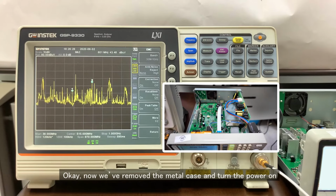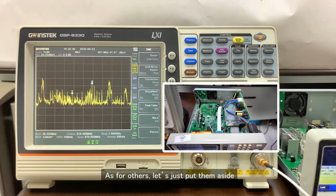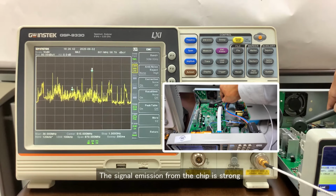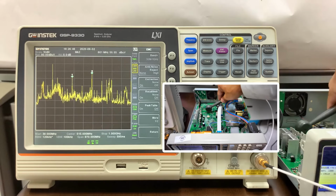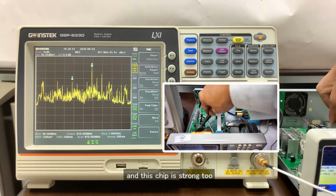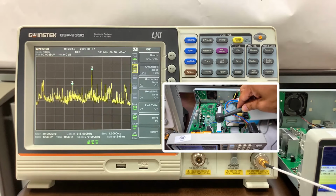Okay, now we have removed the metal case and turned the power on. Please remember that our purpose is to find out where it gets the strongest 400 MHz and 600 MHz signals. As for others, let's just put them aside. The signal emission from this chip is strong, and the nearby circuit is the same. And this chip is strong too. These chips are the key source of the emission.